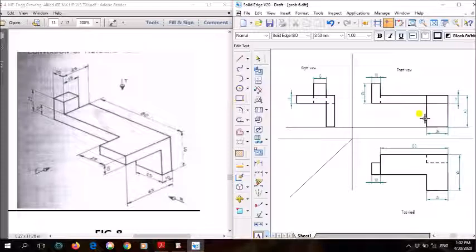For the drawings that you are going to convert from a 3D model to 2D views, that is front, top and side views, this procedure has to be followed. First draw the drawings and then delete the projection lines which are not necessary. Then after you complete all the drawings, showing all the views, hidden lines, everything, you need to do the dimensioning. Split the dimensioning across all three views, and finally complete the drawing by showing the views, that is front view, top view and right view.